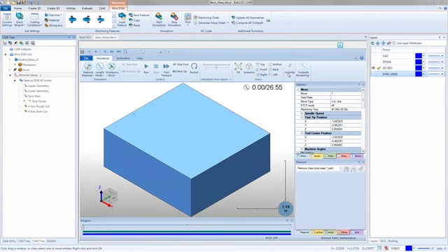So let's go here. I'm going to turn on my machine housing. So this is a little thing. If you go to the visibility tab and your machine housing is turned off, if you turn it on, it doesn't actually show you the housing for the entire machine. It gives you your guides. So it's a little easier to find out what's happening here. So I didn't set up a point or even a start point, but you'll see it's just going to go in and make its cut.